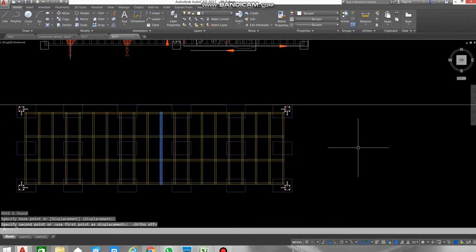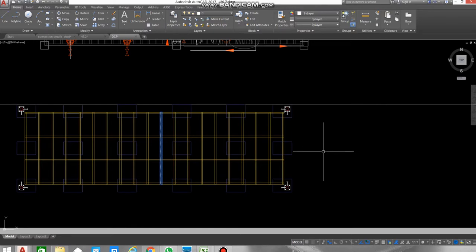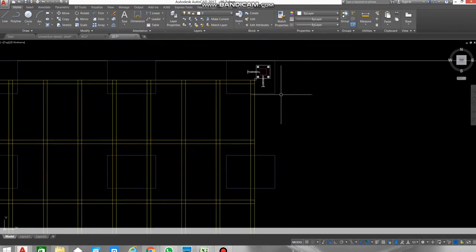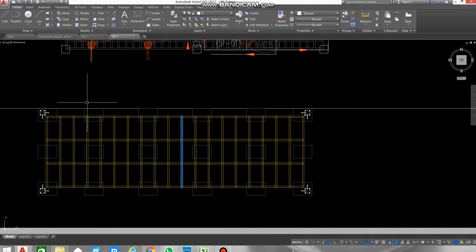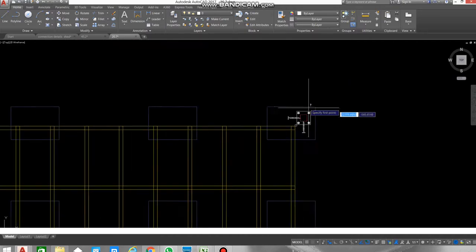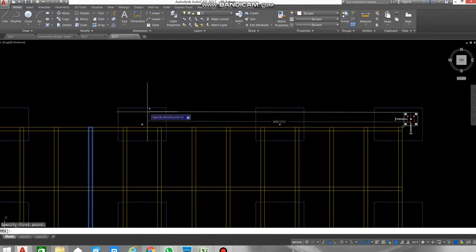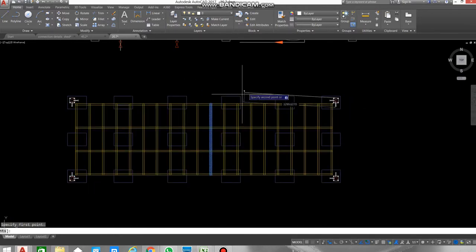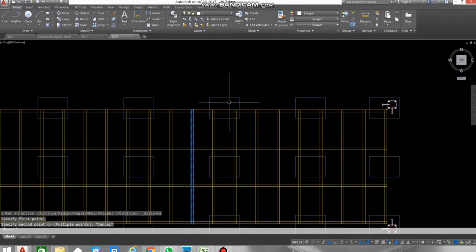All right, now we finish the spacing. This now should be very easy like this. All right, now if you have a spacing here more than 180, okay, you divide them. Now the principle is finished. We don't need this. Okay, after this we move to the second step. The span between the posts should not exceed 4 meters. So here is small, here is good. I cannot go beyond this. So automatically I will have a post here and a post here.